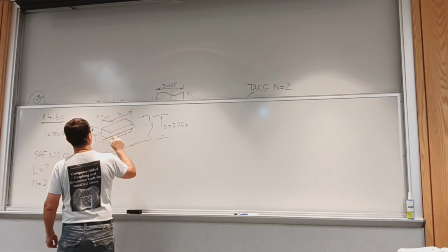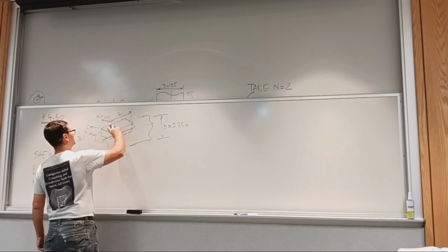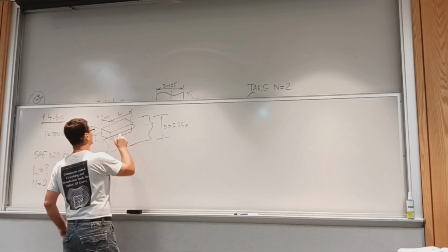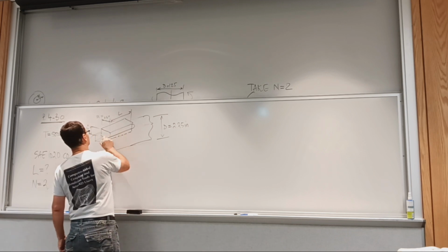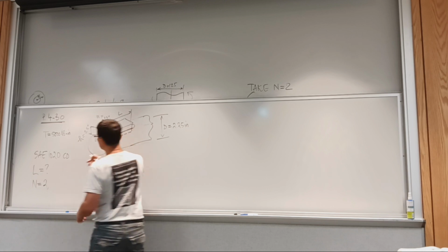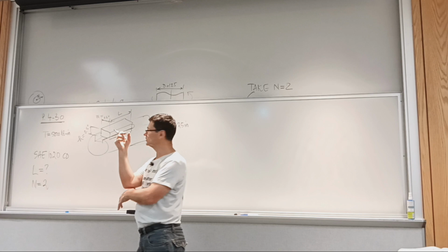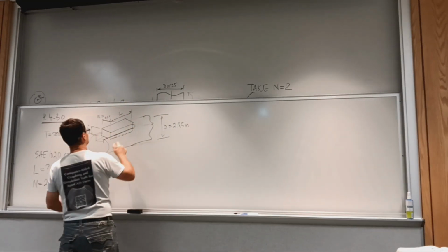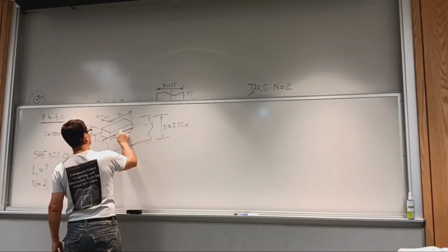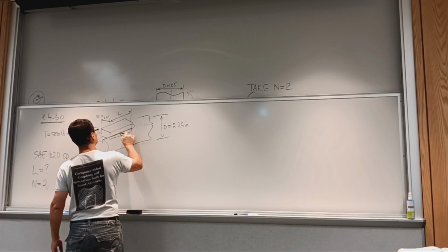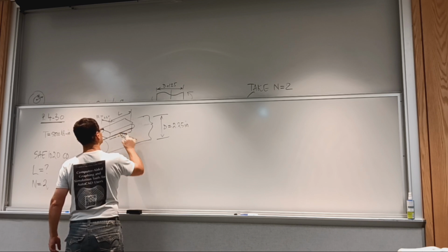So there are slight differences, but we're going to assume the shearing force acts like a key inserted half into the shaft, and the other half interacts with the hub, which is not shown. So we have the shear force F upon the key, right here.